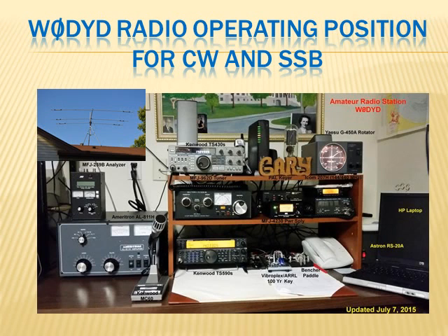So that runs directly into my antenna then, which is the upper left. It's an MA5B Cushcraft mini beam running two elements on 20, 15, and 10, and also a rotatable dipole, which is the center element, and that's on 17 and 12 meters. So we have 5 bands on one piece of coax coming in, so it does not require any switching of the antenna as I'm going from band to band, 20 meters through 10 meters.